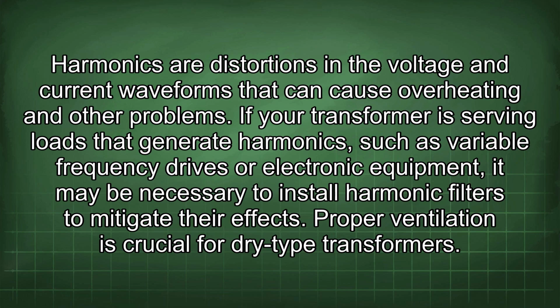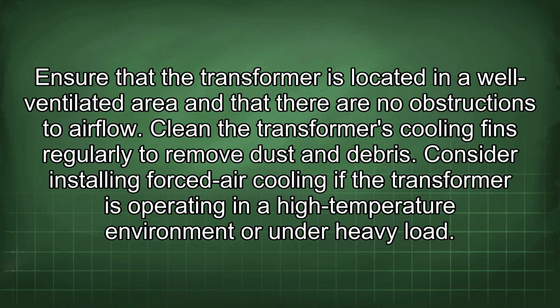Proper ventilation is crucial for dry-type transformers. Ensure that the transformer is located in a well-ventilated area and that there are no obstructions to airflow. Clean the transformer's cooling fins regularly to remove dust and debris. Consider installing forced air cooling if the transformer is operating in a high-temperature environment or under heavy load.